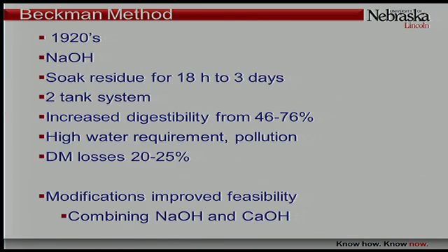One of the first methods that tried to perfect this system was the Beckman method. It was in the 1920s. They used a strong base, sodium hydroxide, and what they did is they filled the tank with enough water to cover the residue that they put in there. And they let that soak anywhere from 18 hours to 3 days. And what they had was a 2-tank system where they'd take this very strong concentration of sodium hydroxide, which was caustic, and they'd drain that to another tank, and then take that first tank with the residue in and add volumes of water until they got rid of the excess sodium hydroxide.